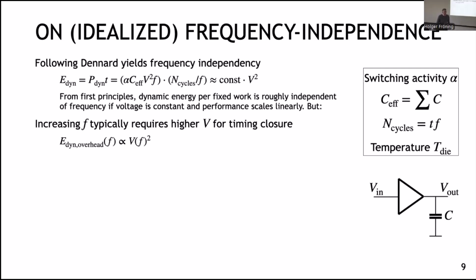So first of all, now the question I would ask my students is if there are any gamers in the room who sometimes overclock their processor at home. What did you do while also overclocking your processor in terms of frequency? The typical student answer would be, we also slightly increase the voltage. And I was like, yes, exactly. If you overclock your processor, you have to increase your voltage because you get nicer slopes, and you basically have a better approach for timing closure. And these things actually work in both directions. So frequency depends on the voltage. If the voltage gets involved, we suddenly have a term in our equation which is voltage squared, which is definitely going to be painful in terms of energy consumption.